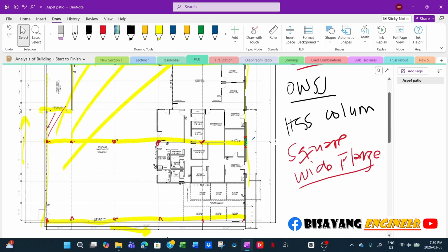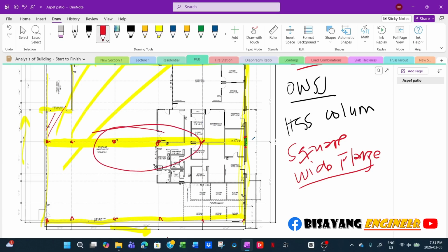But for the sake of discussion, if this is a really long building, then you have to divide the diaphragm to meet the aspect ratio, and then you have to provide a lateral force resisting system in this line here, intermediate. Then you either design this one with moment connections, like this interior, it could be just two span or three span or just single span. Design it as a moment frame so that it can resist, unless you are allowed to have cross bracing there.